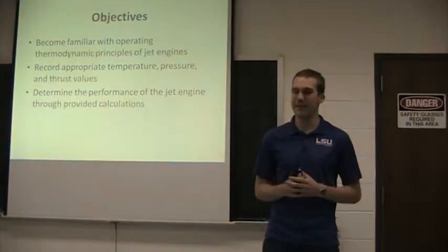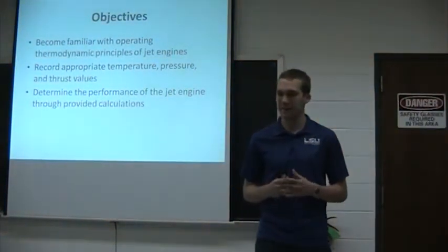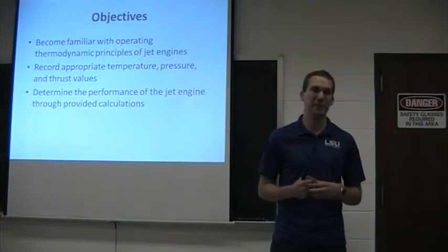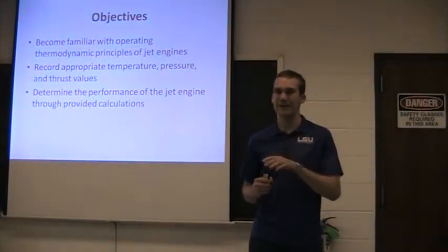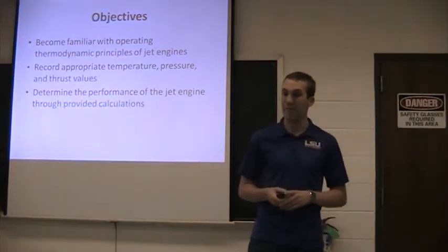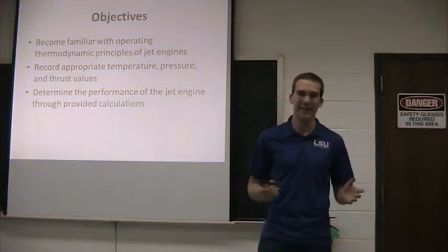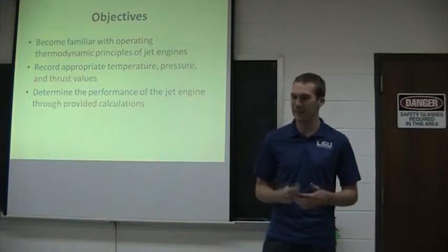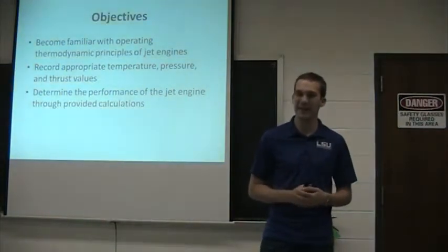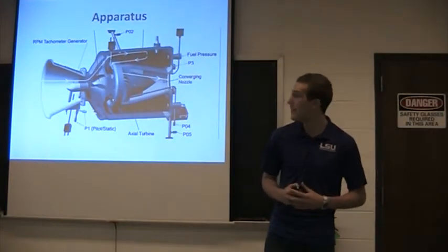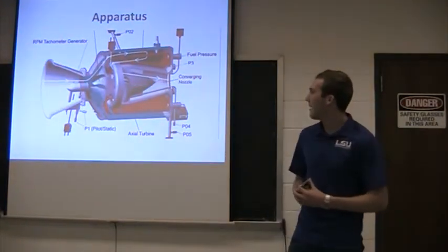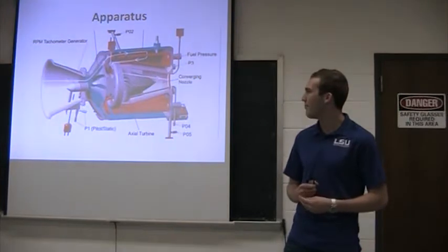So, some of our objectives. The purpose of this experiment is to become familiar with operating thermodynamic principles of jet engines. Basically, we want to dissect the cycle and see different pressures and temperatures at the operating points. We want to do good housekeeping work in a sense. We want to record appropriate temperature and pressures, as well as thrust values, and ultimately determine the performance of the jet engine.